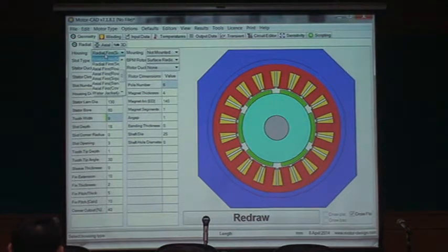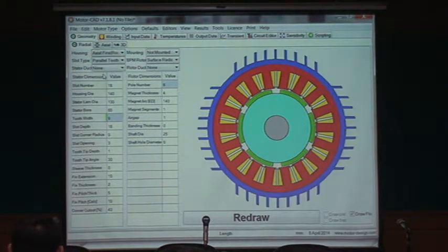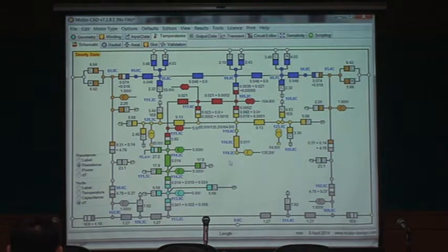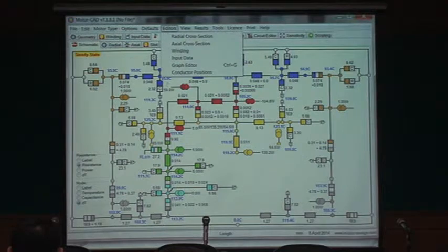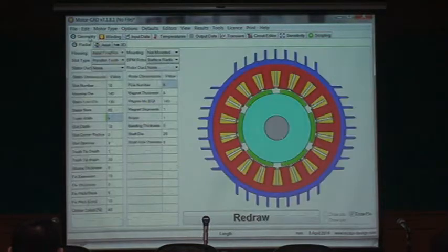Actually, let's put the fin the other way. Actual fins, round like this. And let's look at the temperature here. So now from 140 I went down again to 120, and if I look on the outside I'm at 95, 98, so still a little high. We talked about putting other type of cooling.